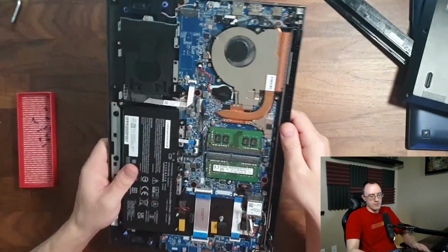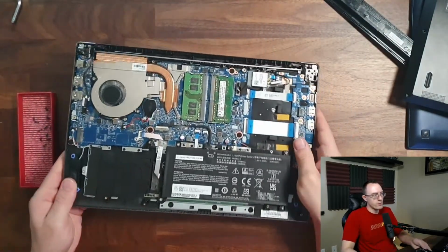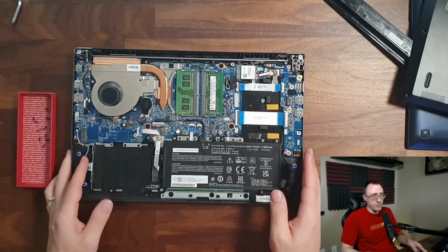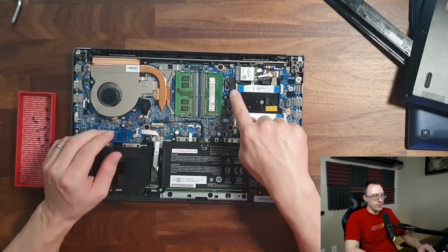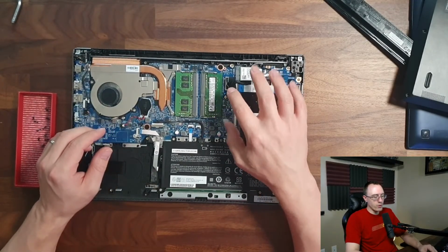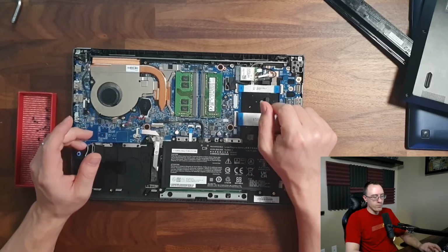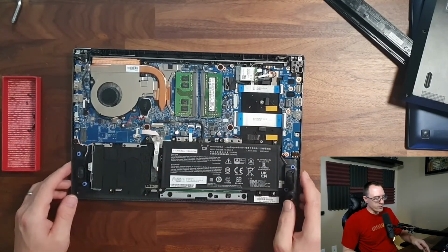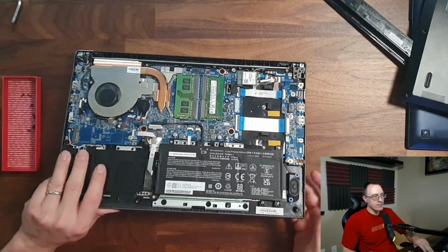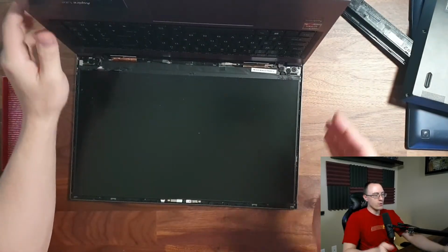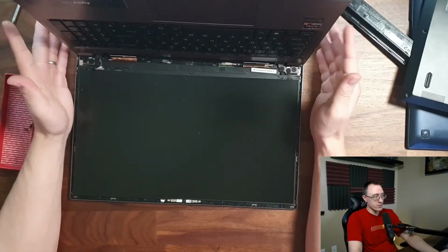So that indicates one of three failures. Failure number one would be the display. Failure number two would be the display cable. Failure number three would be the port on the actual motherboard. Unfortunately, you can't really rule these issues out without replacement parts.